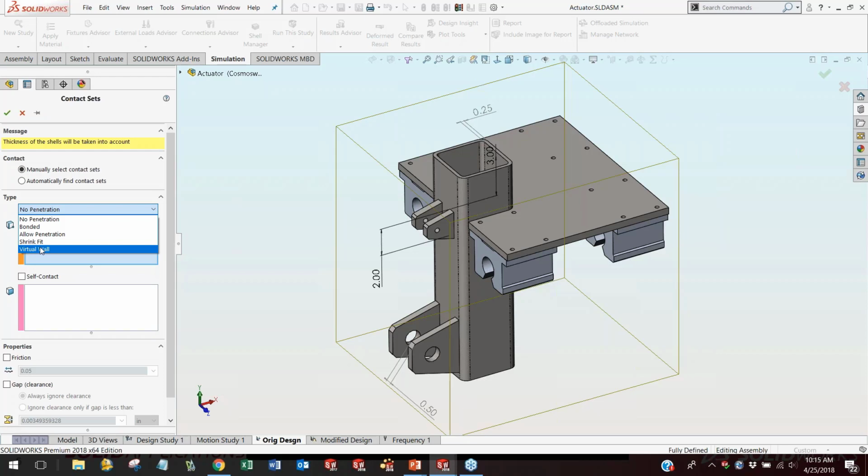Virtual wall is really useful if you want to have something bolted to a large monolithic component that isn't moving. Instead of modeling that component and then restraining it and having to mesh it and solve for it, we just define a virtual wall on a plane, and then we use foundation bolts to bolt something to that plane. So we have a lot of control over our contact sets, and like I said before, we can also handle friction, and we can also handle small gaps.